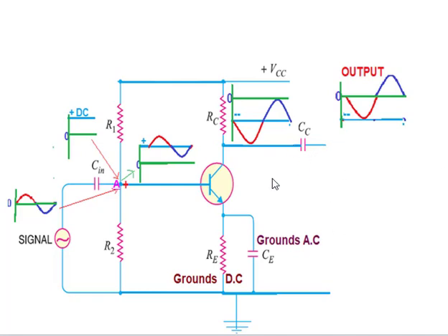Now we go to the working, how it works. When the power is switched on, this resistor R1 and R2 produces a DC voltage here. See, a part of the DC voltage, it is 0.9, a positive DC. At the point A, this potential divider network R1 and R2 plus VCC combinedly forms a positive DC level at the point A.